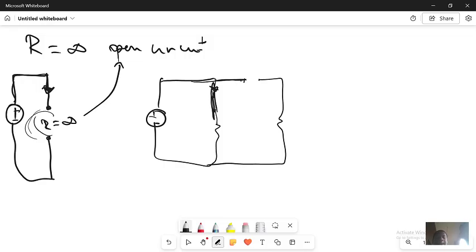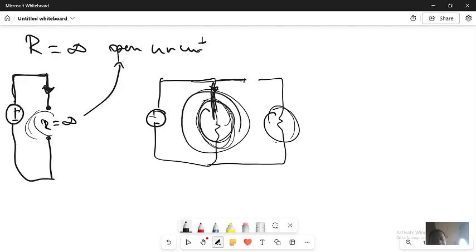If I have a circuit, let's say, with a light here and also a light here in the same electric circuit, and this light is not working but only this light is working, that means the problem is in this part.